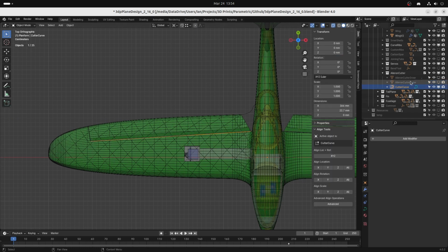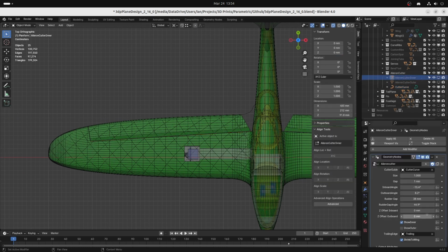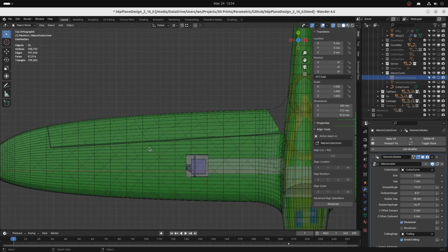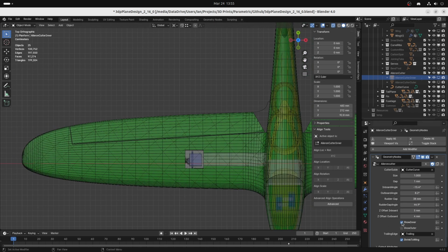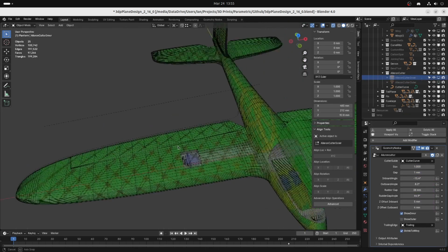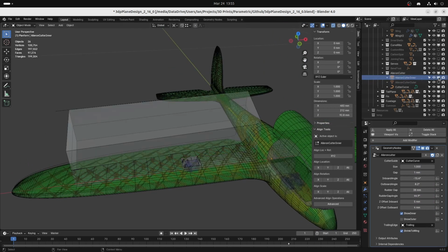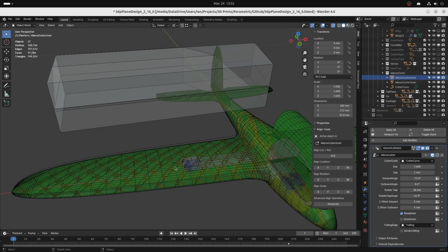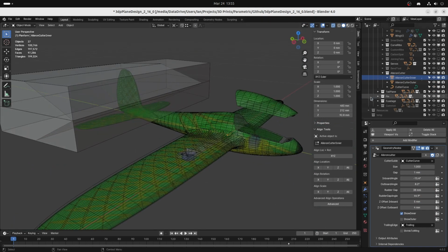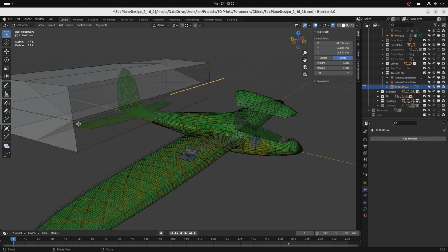The Z offset adjustments allow the endpoints to be raised or lowered to allow for a bit of precision adjustment of the hinge point. The inner and outer cutter shapes use the same geometry node network, so the tick boxes here just select which one this particular object is. Shrink to wing makes the guide curve drop down to the height of the leading edge curve. If you leave this unticked, you can set the height of the cutter manually using the guide curve.